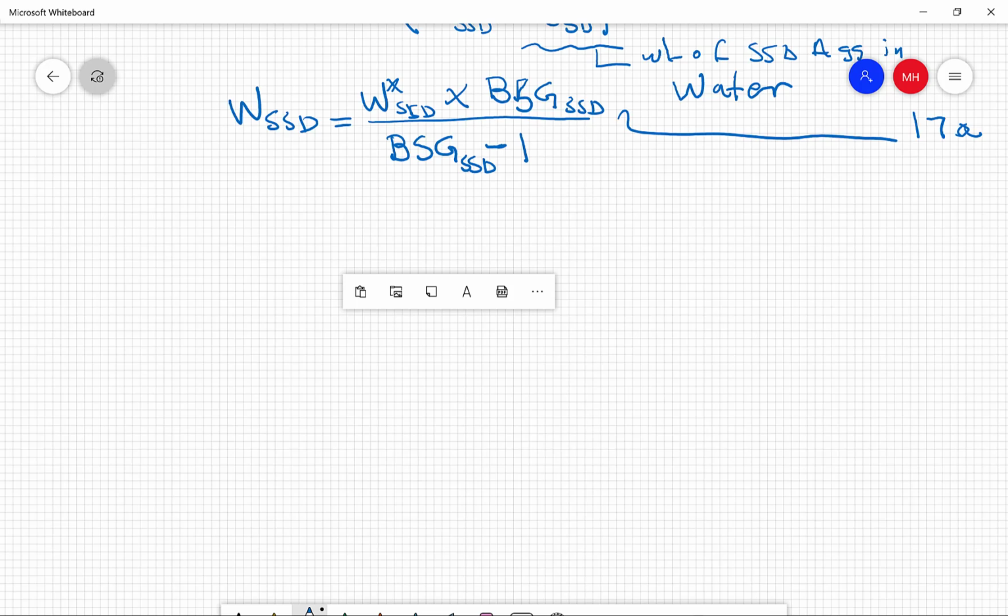So in the case of fine aggregate, equation 14A can be adapted to solve for the water displaced, since the weight of the sand is now the weight of the sand in the stockpile condition. And it can no longer be used in the equation, and we must write it as follows.